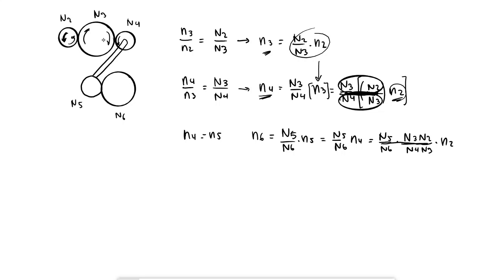Again, what I realize is that what I have here at the top is all the driving gears. So 2 is driving 3, 3 is driving 4, 5 is driving 6. And that's why I have 2, 3, and 5. And then at the bottom I have the driven gears, 3, 4, and 6.